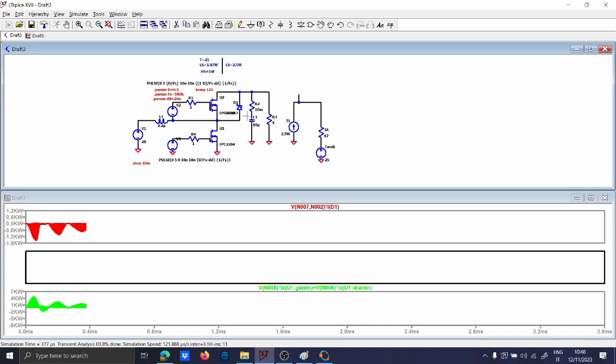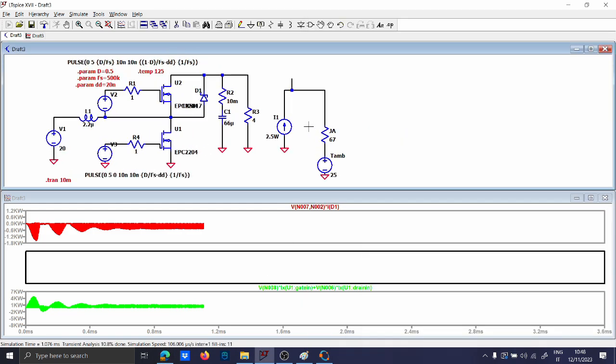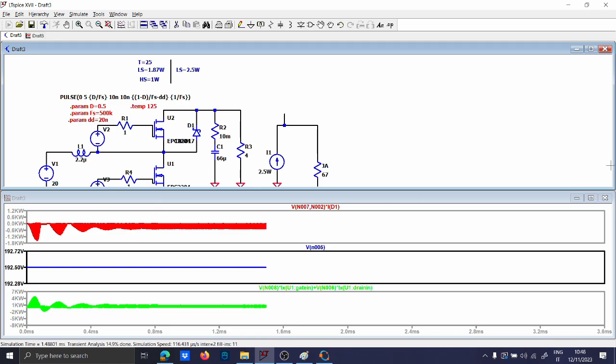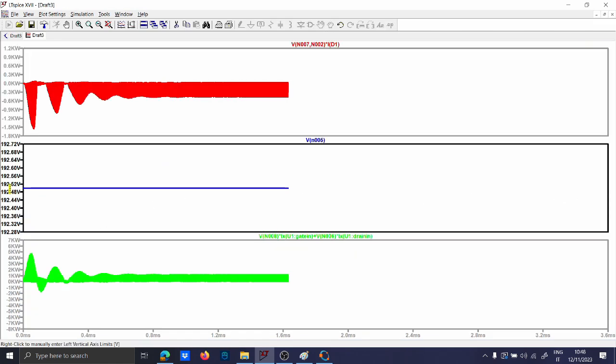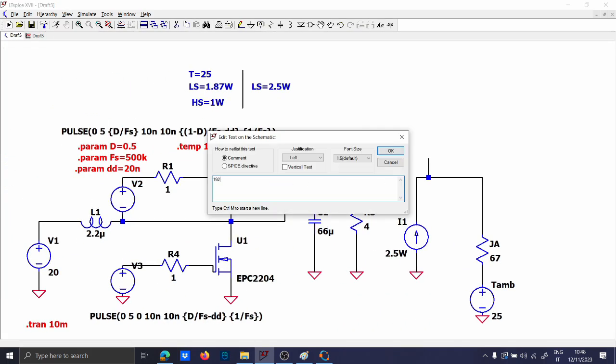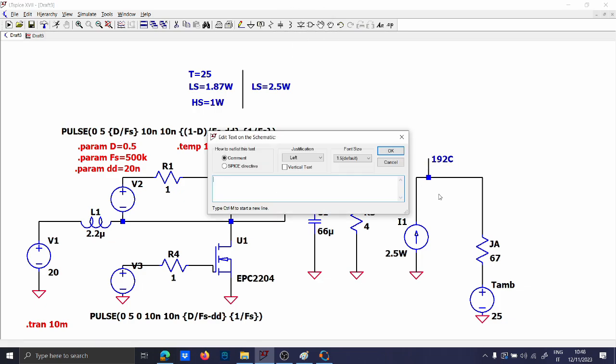At the end of the day, the resistor is so low that you don't even care. So this is the temperature, 129 degrees. Now, of course, this is a temperature which should make you think to use a heat sink, and so 122 degrees is an exaggeration. You have to use a heat sink. Okay.